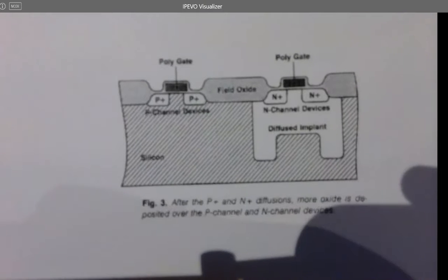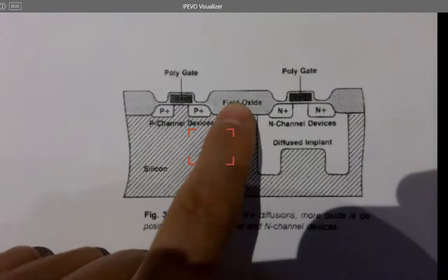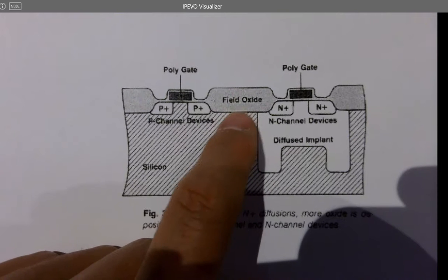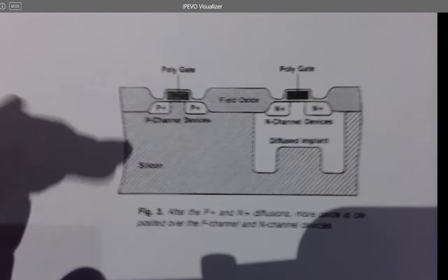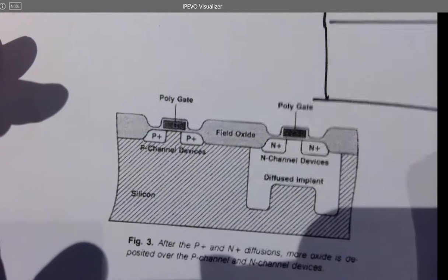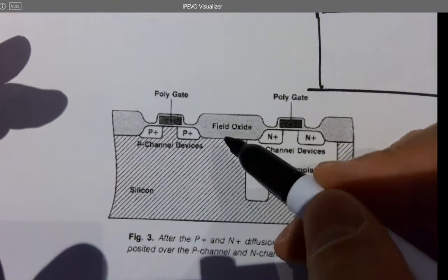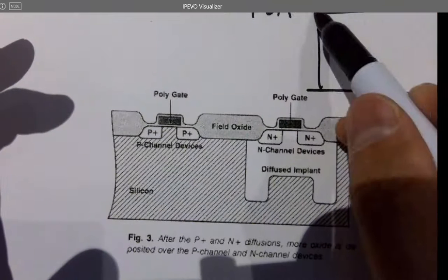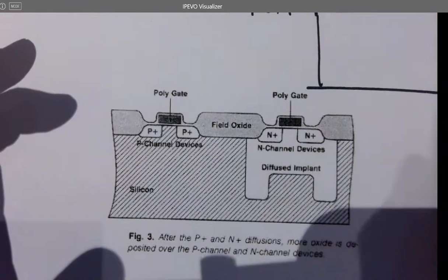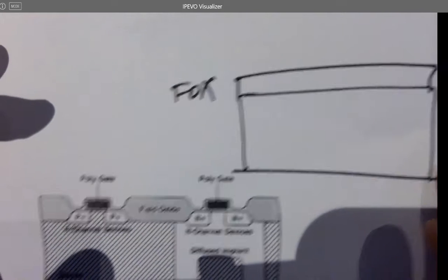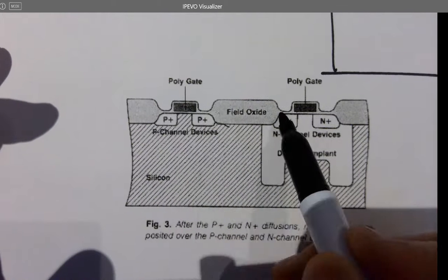But you should realize that in the real world, the oxide layer directly on the top of the silicon substrate is not like, for example, here's a substrate. So fused oxide, just silicon oxide, okay? It's FOX for short. The FOX is not directly just sitting on the top, it's like this, getting into it a little bit.